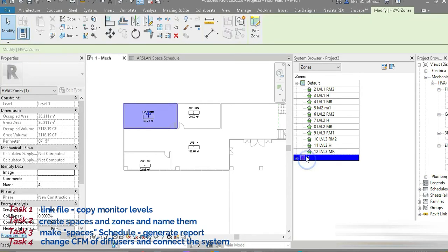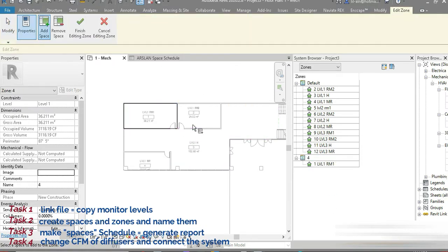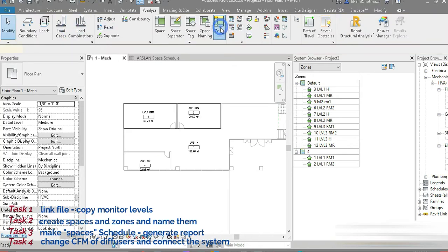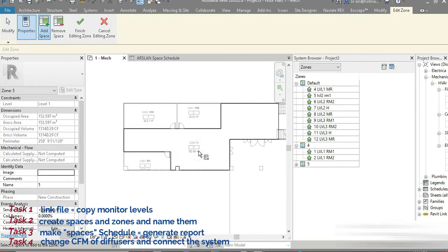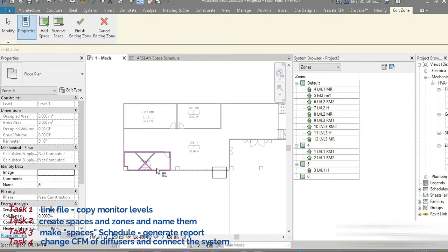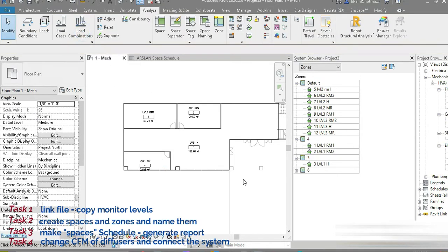So why is this acting a bit weird? For example, this is the zones, right? Let's go to Edit Zones right here, and in this one now we include both of them. Let's press OK. After that, let's go to the zones again, and let's create another zone. So this is going to be the 5. Okay, let's go to zones right here, and let's create that zone. I don't know why both of these zones were automatically included and it was acting a bit different.